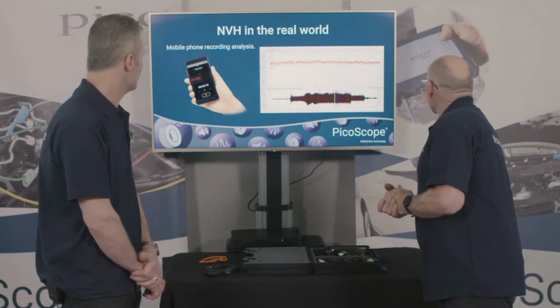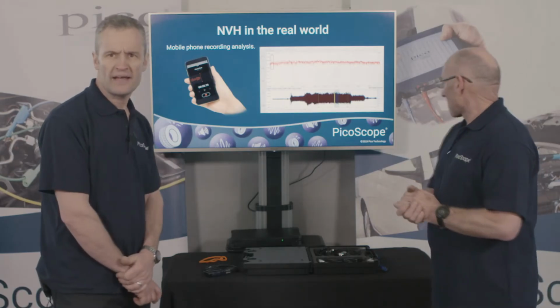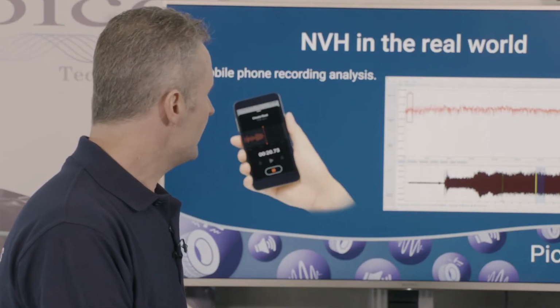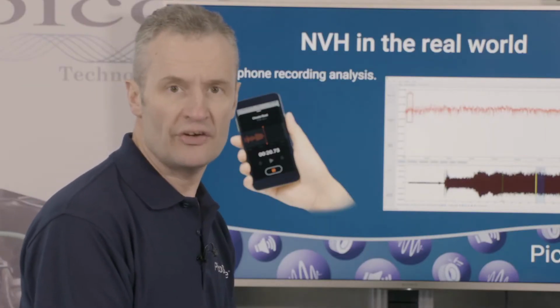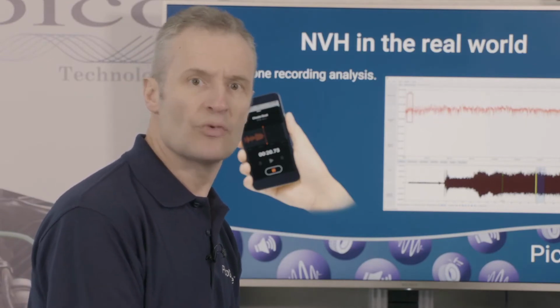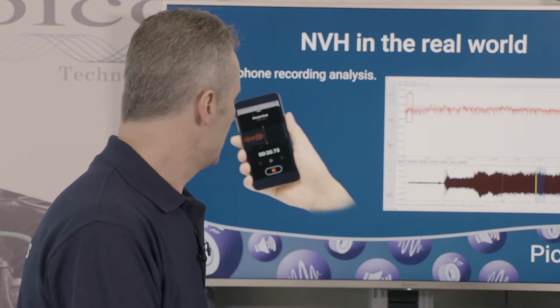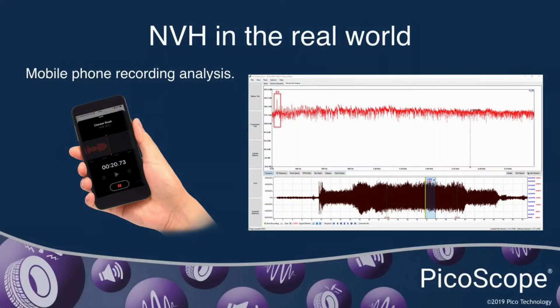This customer is complaining of a whine from the engine. So that peak we can see certainly is E2, two combustion events for one revolution of the engine. Well, E2 is twice engine speed. We cut that in half, and we can determine from this what their engine speed was. We can also determine that peak at E2.